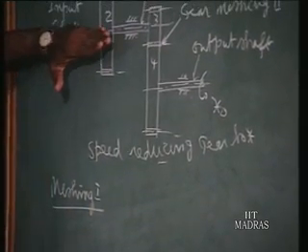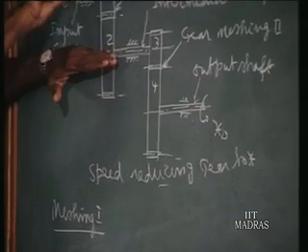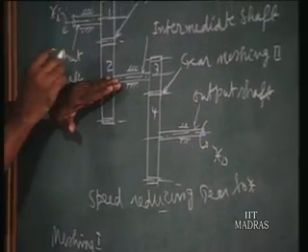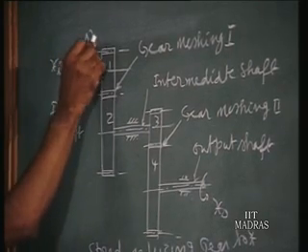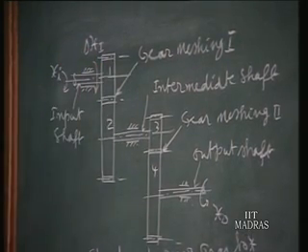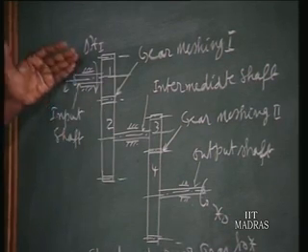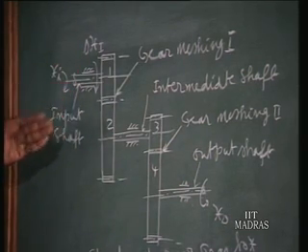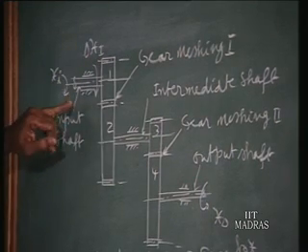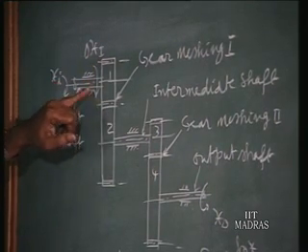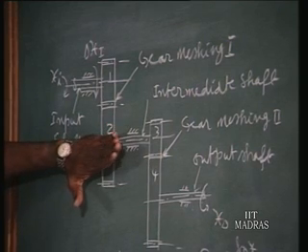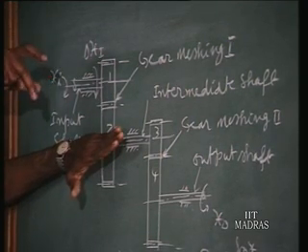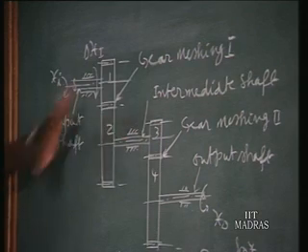Hold the gear 2 and rotate the input shaft. This is your input shaft. Rotate it, and there you will have a free motion of delta x1. This is the backlash. That much rotation will be there. From the middle, you will have the rotation delta x1 this side and the other side. So delta x1 is the play or the backlash in the input shaft, due to the backlash at gear machine 1. We are holding this fixed and we can rotate plus delta x1 and minus delta x1 from the middle position. That is due to play.